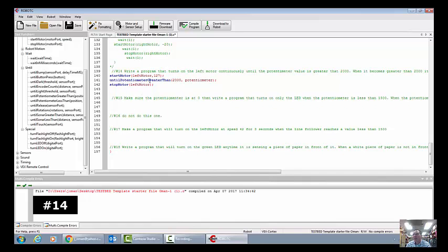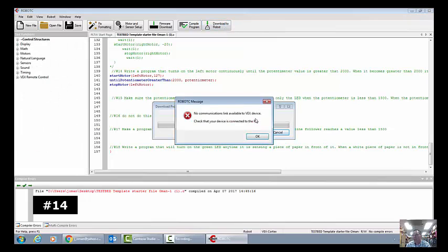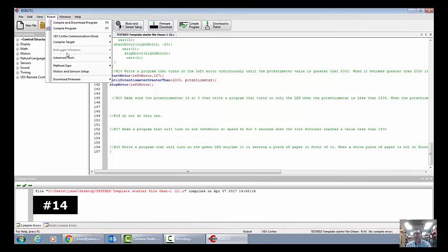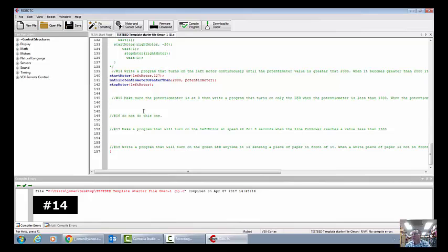Okay, to truly make this work, make sure your potentiometer is turned all the way down to 0 when you download this one. Okay, it'll download. I get an error message because I'm not actually plugged into Cortex right now. Okay, but when this downloads, you should then go back to the robot menu. The debugger window is available if the start button is out here. You slide over from debugger and you turn on your sensors. It'll tell you your sensor value down here at the bottom. Okay, so you know exactly what the potentiometer is reading on your robot. So make sure of that, please.